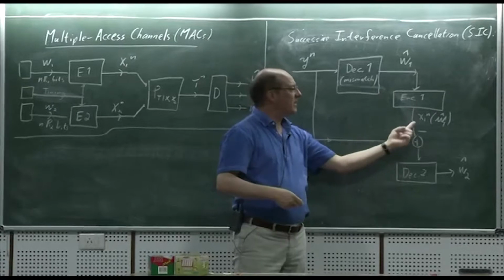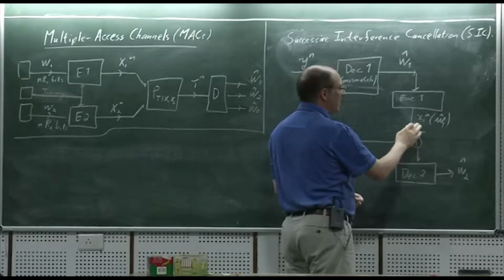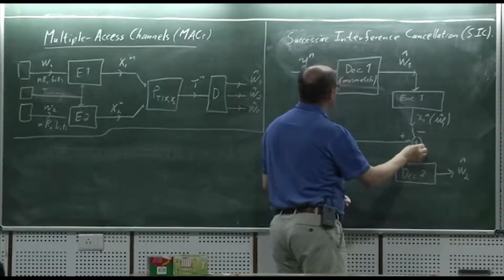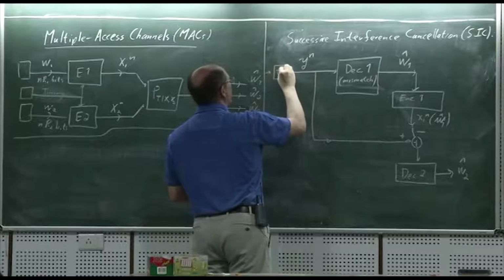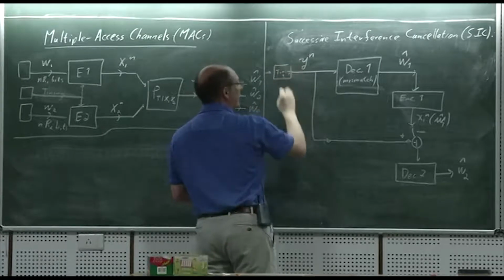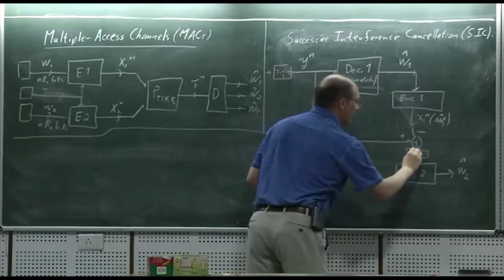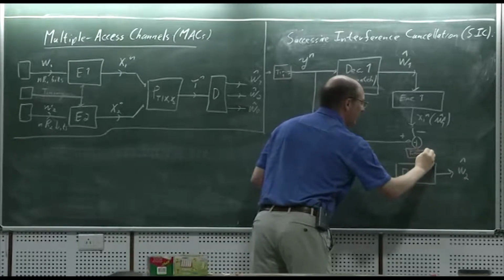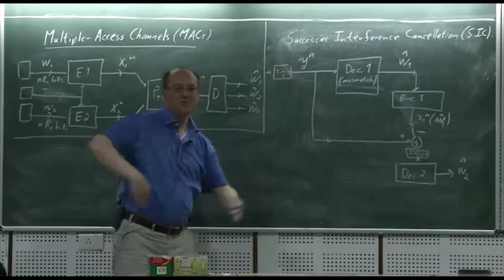After you do your decoding and re-encoding, we have to add another box. You need two boxes basically, timing for user 1, and another box that again interpolates so that we get the timing for user 2, right? What I mean by these boxes is just sinc interpolation for band-limited functions, right?